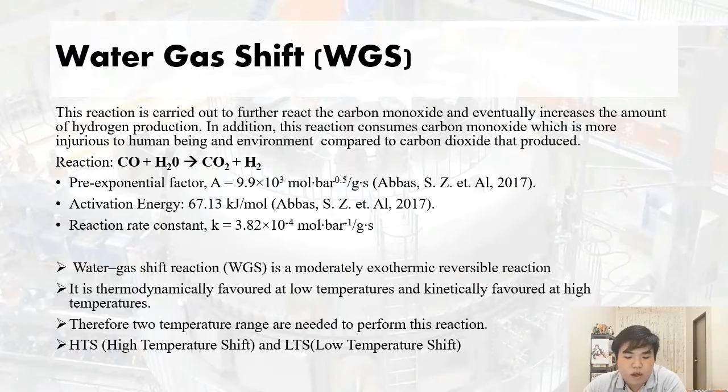The water gas shift reaction is a moderately exothermic reversible reaction that is thermodynamically favored at low temperatures and kinetically favored at high temperatures. Thus, it is performed at two temperatures, which are the HTS, high temperature shift, and the LTS, low temperature shift.